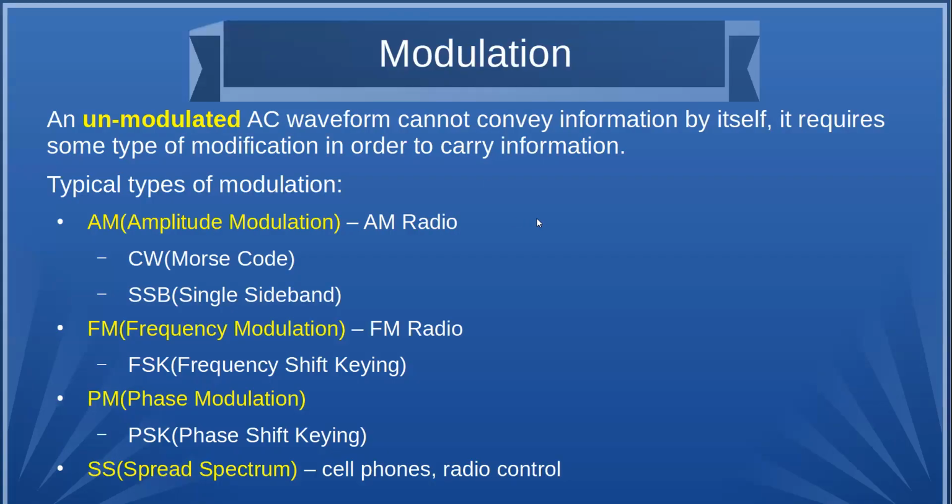Okay, so we got amplifiers, we got oscillators, need to do something with them. So we can convey information on a waveform by what we call modulation. If you just have an oscillator connected up, as part of your transmitter to the power amplifier, putting out a carrier, people will see the carrier, but there's no information transmitted. Until you go to CW and you turn the carrier on and off, and then you can do Morse code.